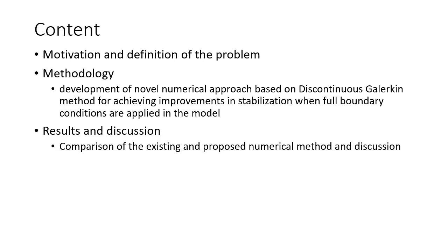The results are obtained on the simplified standard drift-diffusion model equation system and will be compared with existing numerical methods on such a simplified model in the results and discussion section. As a conclusion, this new numerical approach shows less sensitivity to the form of boundary conditions, and in future work we will try to improve this method by implementing Scharfetter-Gummel numerical flux.